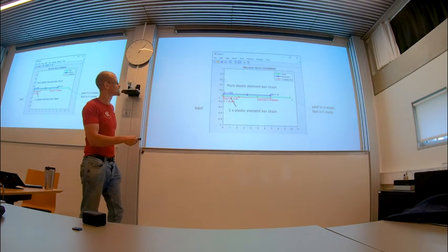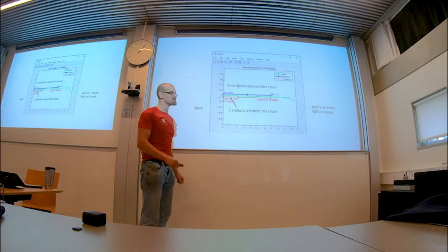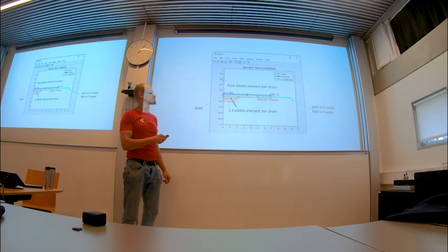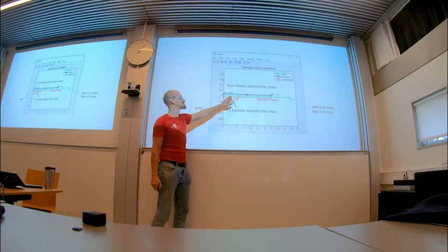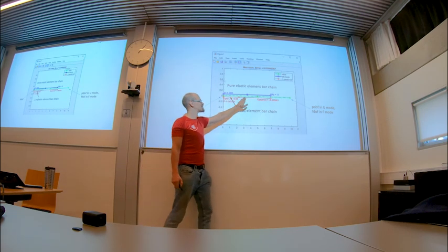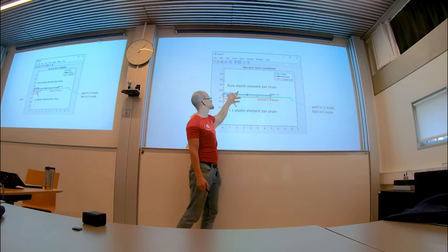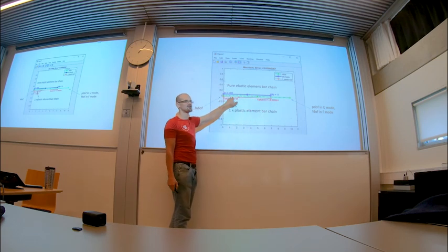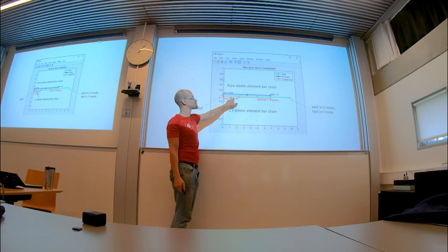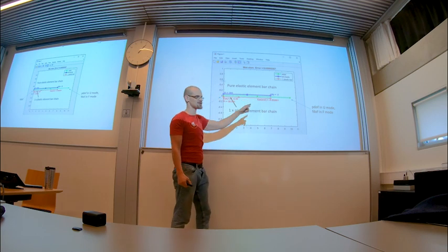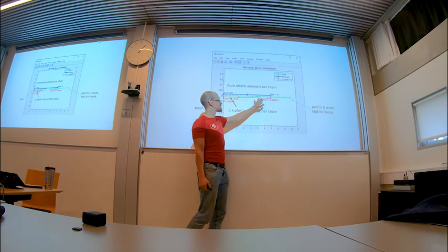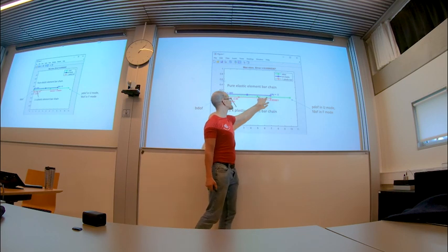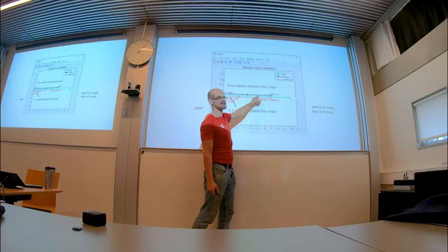And in that MATLAB code, you have a super simple system, and it has the option to increase the number of springs. There's technically one spring that is elasto-plastic, and one that is pure elastic. This is the same spring system, it's just this one is fully elastic, this one has this spring modified to be elasto-plastic. And then you can choose any curve you want to apply on this one. I leave this one elastic because I want you to see that the elements interact with each other. So if you apply a force, the length of this one and that one will be the same.